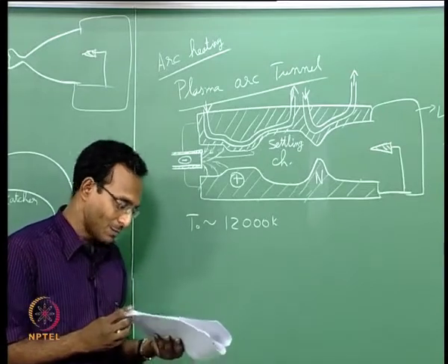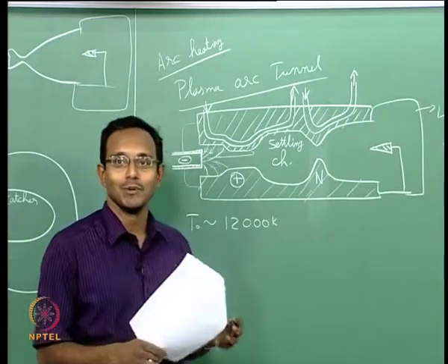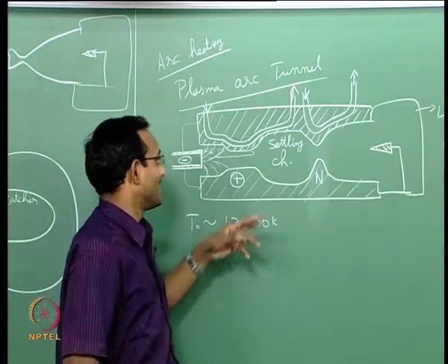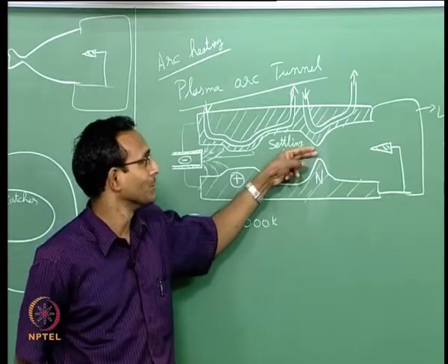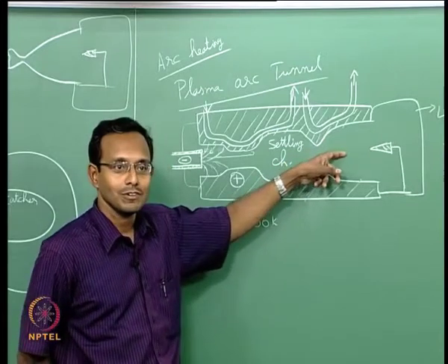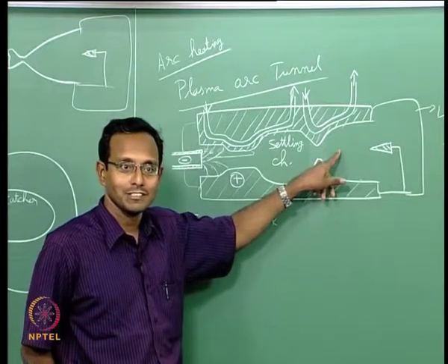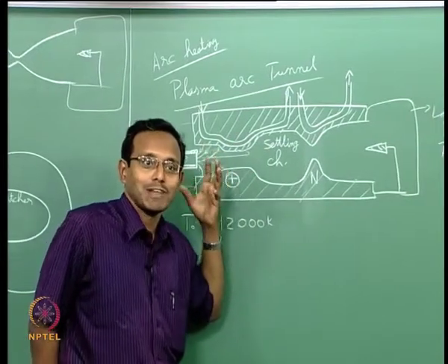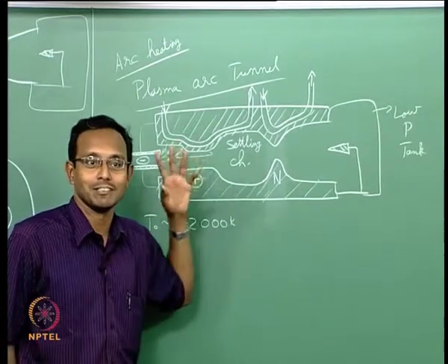Okay. And one more thing, I am jumping myself out of this course content currently. If I say that there is plasma, high pressure, high temperature plasma that is coming through this nozzle, once it goes to supersonic flow, the pressure and temperature becomes lesser. At those conditions, the plasma cannot exist as plasma and it has to recombine to form neutral molecules, neutral atoms in this case if it is argon.